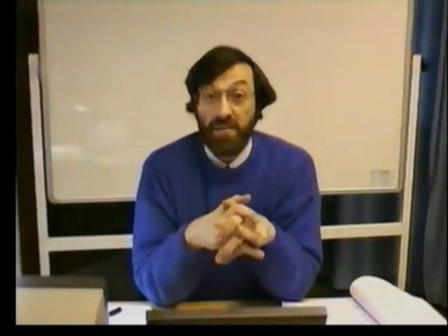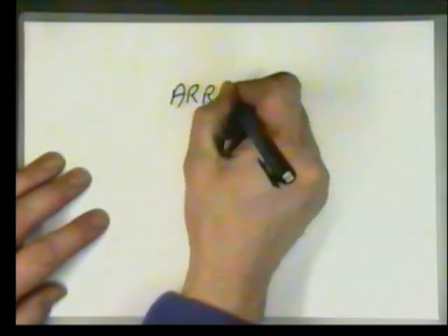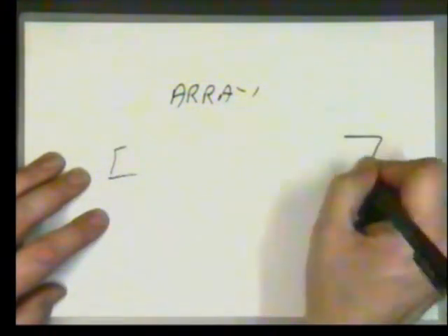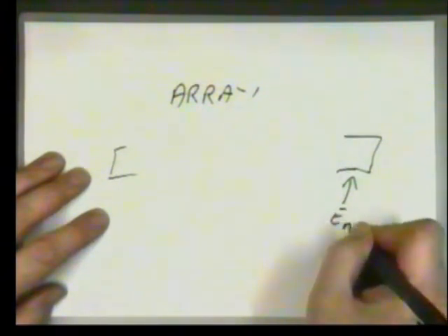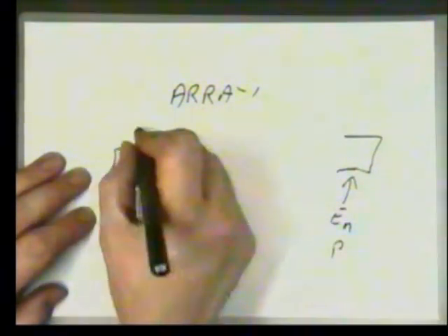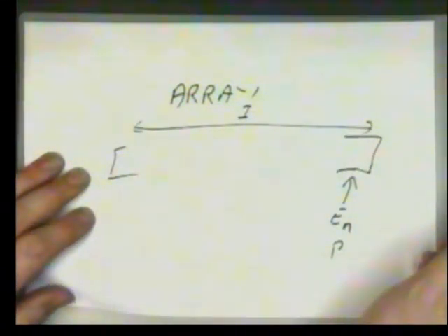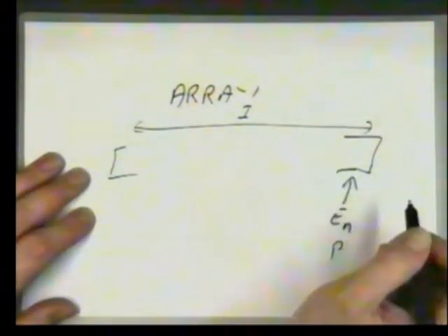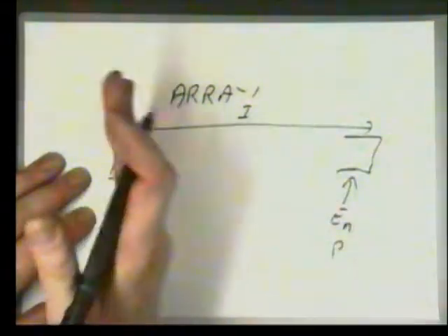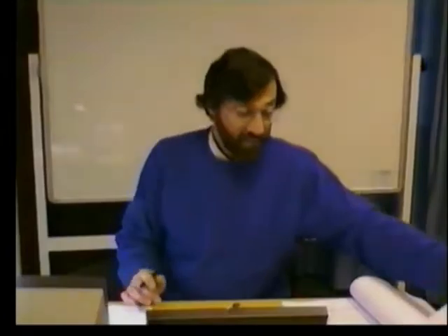And in fact, PI controllers really come into their own with the advent of microcomputing, where we have these data structures and we use it. So what we tend to do is that we would have an array into which we store our errors. The most recent sample EN is used for our proportional term, and the sum of the array is used for our integral term. So we get proportional integral control, but with only the most recent data, not historic data. So there we have proportional and integral control.